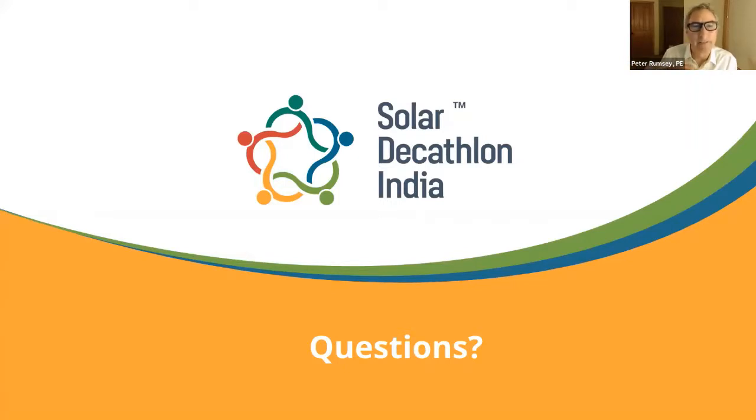So it might be that in Hyderabad, which has dry, hot days and also hot, humid days, the maximum cooling load is when it's, let's say, 32 degrees Celsius and humid, but the highest temperature of the year might be 35 or 40, right? But that 35 or 40 degree day is dry. So the maximum load on ventilation is not always when it's the maximum temperature.